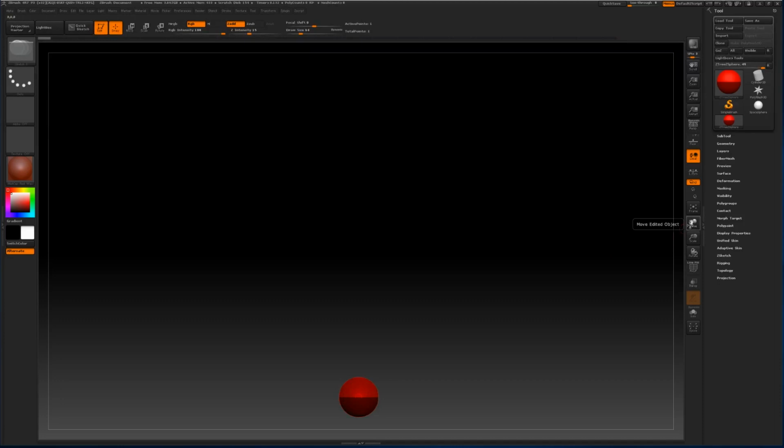Now we're just going to create a Z-sphere base without using ZTree. We'll just do this manually. Make sure that you have ZSketch. Typically I think this defaults to ZSketch anyway, but you're just going to drag out a new Z-sphere on top of the first Z-sphere. And you'll just hit OK because we are deleting that undo history that we just went back on.